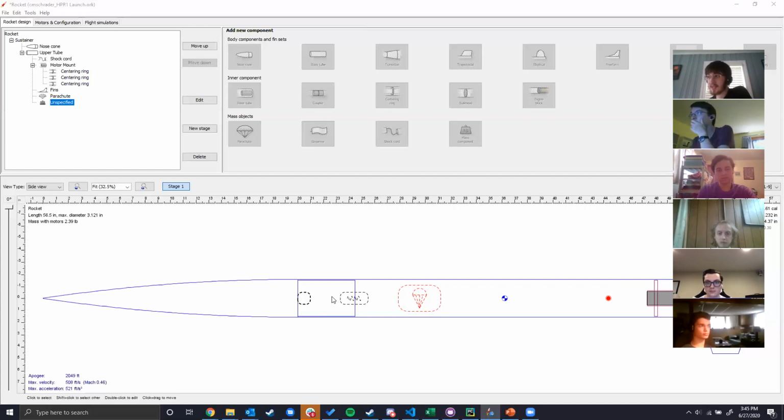One of the important things is that you should be able to hold your rocket by the top and not have the shear pins shear. If your shear pins shear in that case, then you don't have enough or aren't using strong enough shear pins. Your shear pins need to be able to hold the rocket together at least while it's in flight.